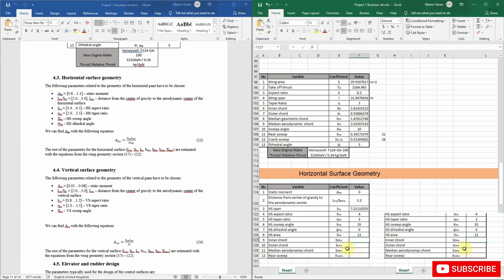So now we need to estimate the inner, the outer, and the median chord. As we did with the wing, the inner chord will simply be equal to the taper ratio multiplied by the outer chord. Then the outer chord will be equal to, in brackets, the area of the horizontal stabilizer divided by the span of this stabilizer, okay, and I will close it, and this I will divide by 2. So here we are getting about 0.9.